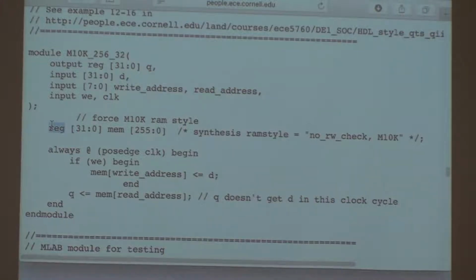So you just give it a 10-bit address, and data would come back out of the array of 4 M10K blocks, and you don't have to know there's 4 blocks. The output multiplexers and the addressing are generated for you automatically to concatenate memory blocks into larger arrays.